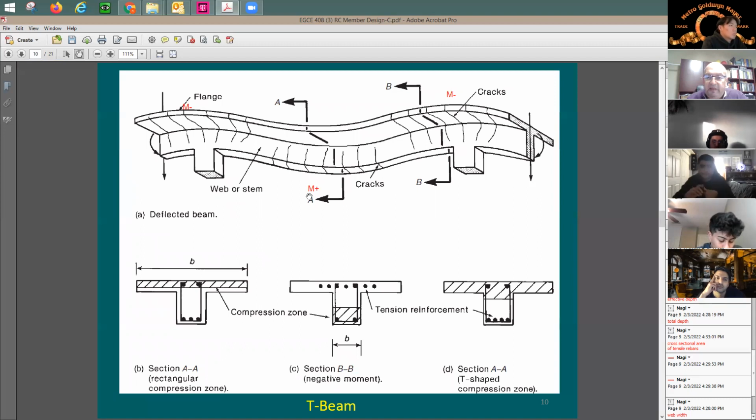Now this beam is gonna be supporting actual loads, meaning that we need to add some reinforcing. So in a case like this, I'd like to add some reinforcing here in the bottom. It's gonna be my main reinforcing to take the tension, and above the column, I'm gonna be adding some reinforcing. So the reinforcing here is to resist the tension. I'm gonna put it here in the tension side. So here the tension side is gonna be at the bottom of the beam because I have positive moment, and in the top of each column, I'm gonna have negative moment, meaning tension in the top, and there I'm gonna place my main reinforcing bars. Okay, yeah, it makes sense. You put the rebars in the tension side.